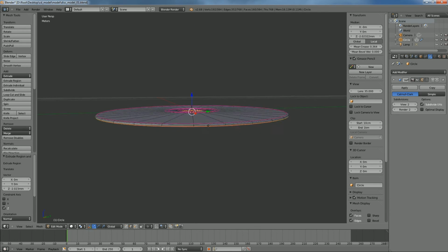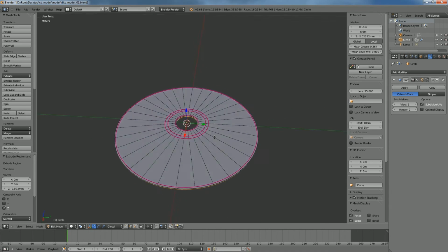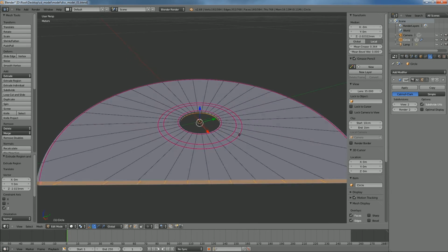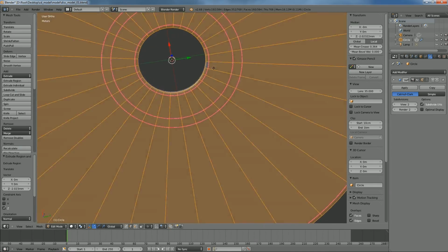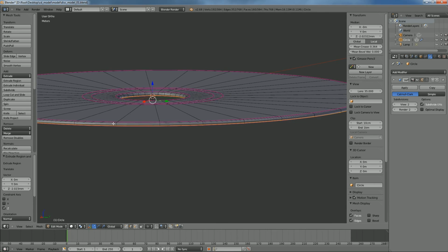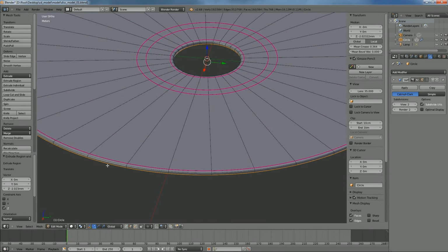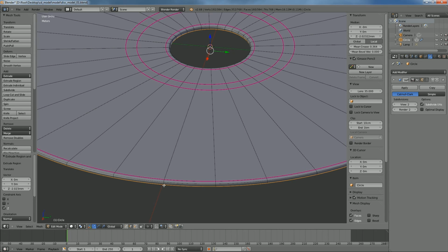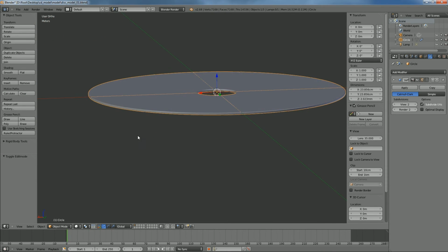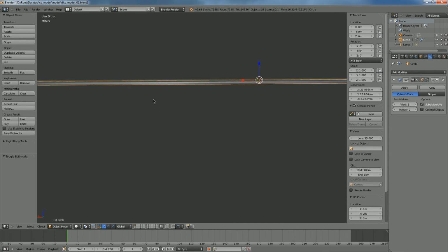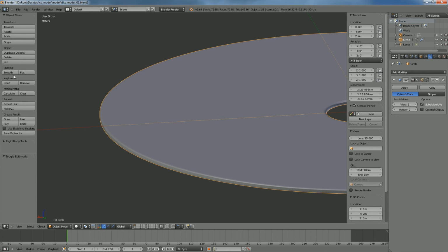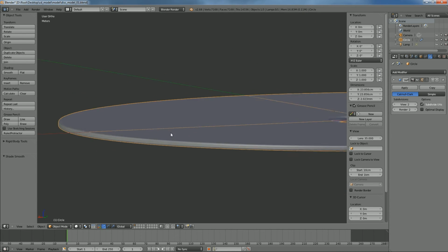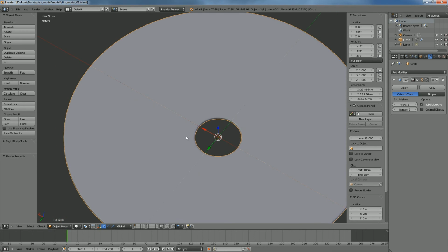It's going to estimate about 1 to 2 millimeters. Yeah, that should be about good. So we have that. Let's go to orthographic so we don't get the clipping in our way. And you can kind of see that it's getting folded over here with the subsurf. So if you didn't want that to be so extreme, you could go ahead and put a couple retaining edges here on the side. And now you can see we've got this nice beveling as opposed to it just melting away on the edge. And we'll give the smooth shading. There we are. So we have this lovely disc.